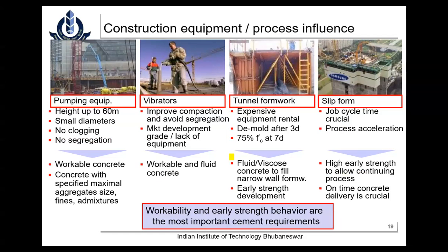Definitely, you see this in some construction scenarios in big infrastructure projects. So we definitely need to look at this. These things have to be solved beforehand. This compatibility issue has to be solved beforehand. Let's say somebody has finalized a particular brand of cement. To meet that requirement, the admixture manufacturer has to come up with the right product so that it will be compatible with the cement, and there should not be any issues in the future. This is one big problem.